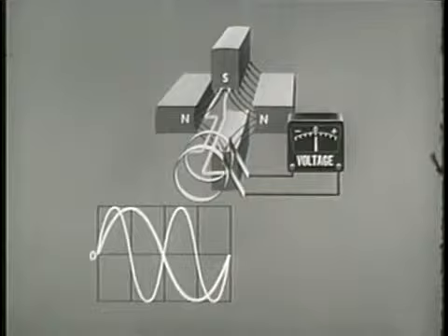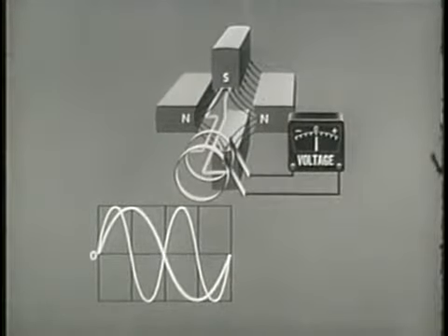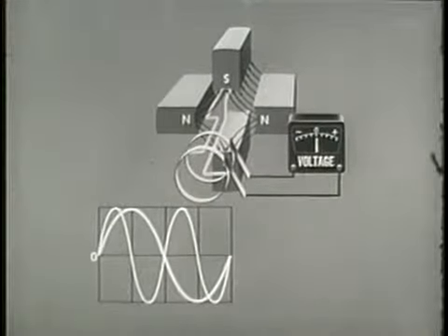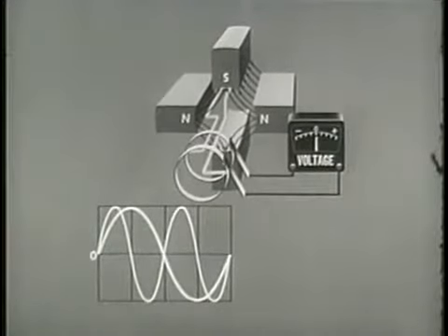In one complete revolution of 360 mechanical degrees, the armature passes through two fields equal to 720 electrical degrees, and 2 cycles of AC are generated. Frequency can be changed in the AC generator by the introduction of additional magnetic fields.